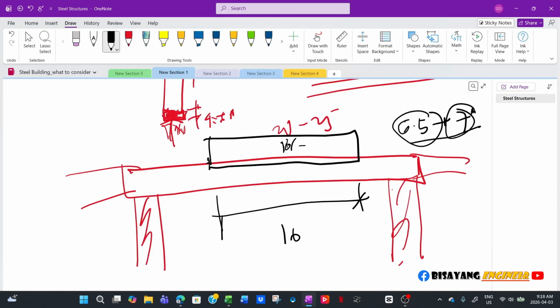So now you will have an axle load coming in and out of the building. Then all you have to do is determine the estimated axle weight of a truck. For example, if it's a dump truck, the lead axle would be smaller because this is where the driver is. This is usually lighter compared to the weight carried by this one, even just the bare weight.